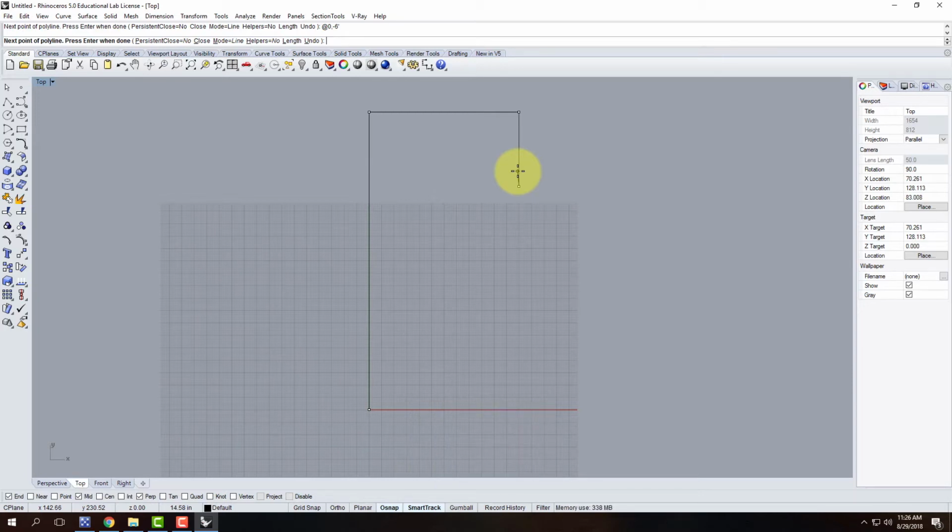The alternative would be the absolute coordinates. In this case, it would be 12 feet, comma, 18 feet. But you'd have to do the math to figure out, oh wait, it's 24 feet up minus the 6 feet. You get the idea. So doing the relative coordinate makes it a little bit easier. So just @ 0, comma, negative 6 feet.